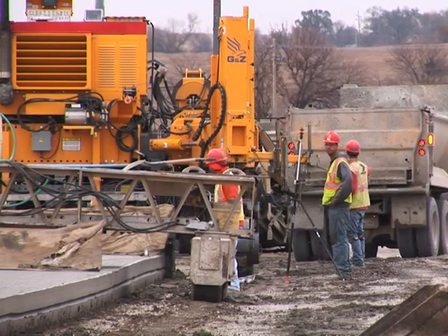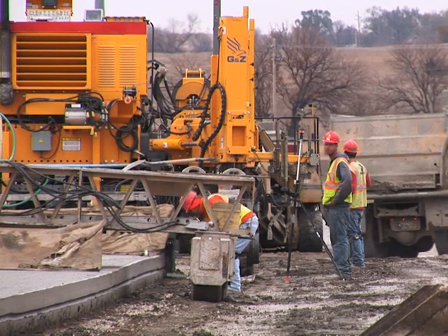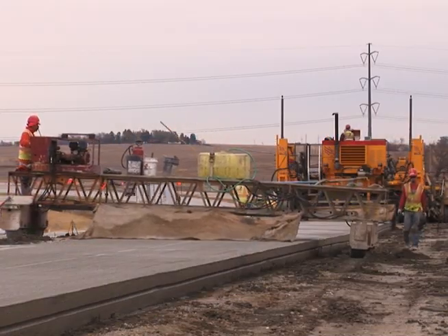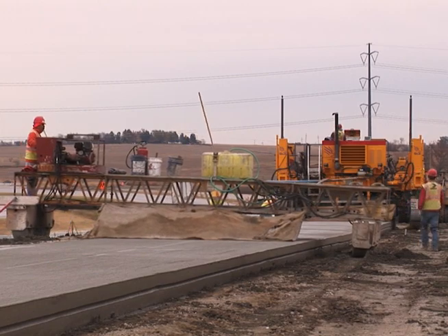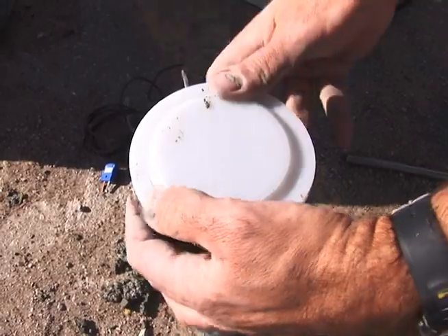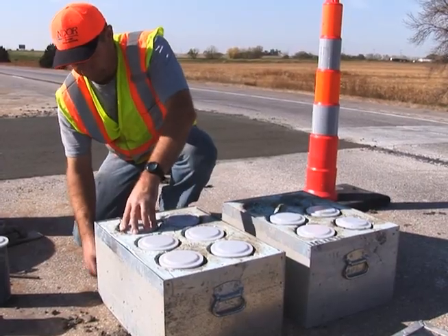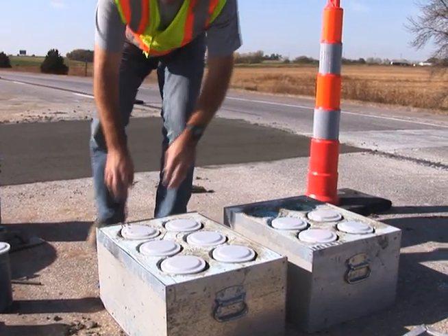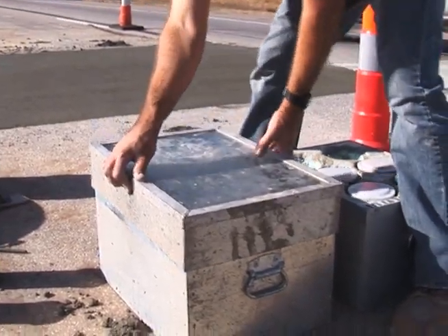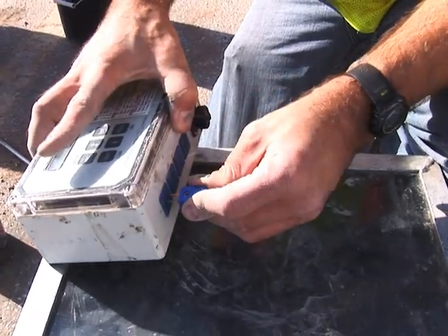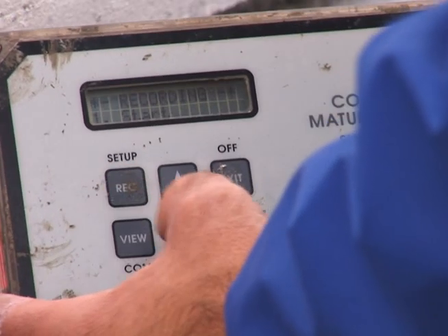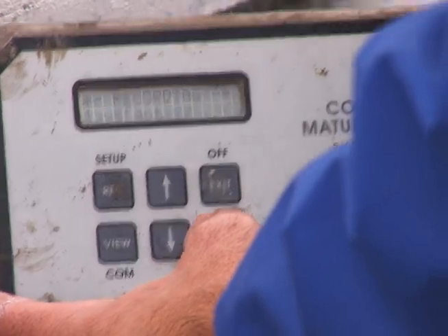The contractor may request the use of the maturity method on a project basis. The request shall be made in writing to the Materials and Research Engineer. The Materials and Research Division, or a certified consultant, will establish the relationship between mixed strength and time temperature history to estimate real-time in situ strength. This relationship is represented by generating a curve, which is then submitted to the project engineer and field inspectors.